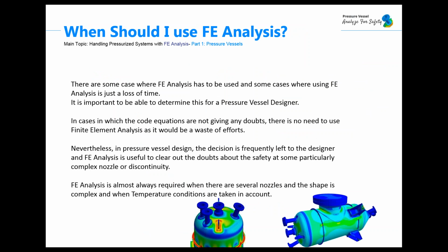Hello everyone, so I'm back. I'll have just a few words about FEA in pressure vessels, because if you have ever used FEA, you know that it's not always useful to actually perform it, and in some cases it's just a loss of time. So it's important to be able to determine this when you are working in pressure vessel design. And in cases in which code equations do not give any doubts, then you don't need to use finite element analysis, because it will be a waste of effort. But in pressure vessel design the decision is frequently left to the designers, and FEA is useful to clear out doubts about the safety at some particular complex nozzle or discontinuity.